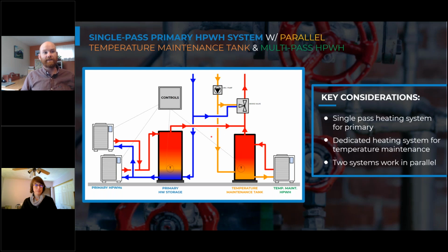So that's why sizing is really one of the key design considerations that we're going to discuss next, because if we're not cycling water appropriately through this tank, we can essentially have this tank drift down in temperature. So this once 140-degree water is now 120 because there just hasn't been that much use and it's oversized initially. So sizing is really critical.